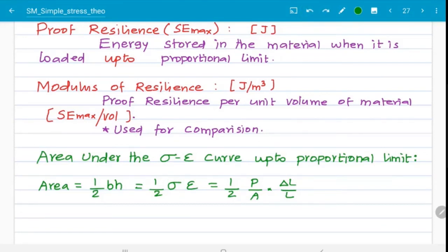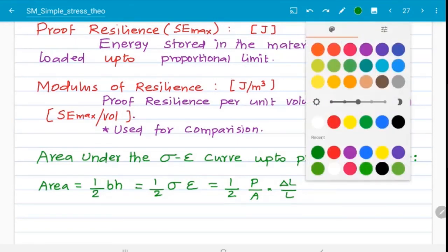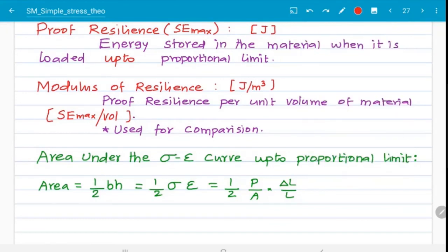That's it. Now, which type of load is applied in the UTM? Tell me, uniaxial tension test. Quick. Which type of load is applied? Gradually applied load. What is the effective gradually applied load? Effective load or average load, anything. P by 2. Okay. Right.